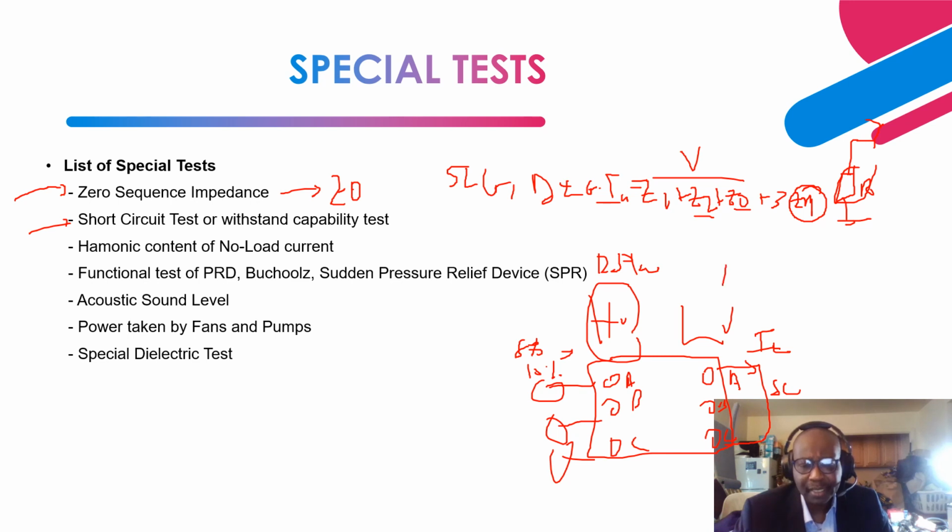At the same time, during the test, the copper losses, I squared R, or the load loss, is measured utilizing the voltage measurements, the current measurements, the voltmeter, the ammeter measurements, and also you can have a wattmeter that is in phase A and phase C for those measurements. So all these measurements are put together to obtain the total load loss.